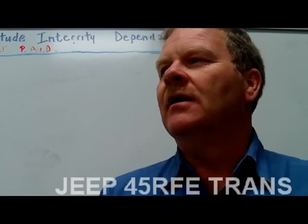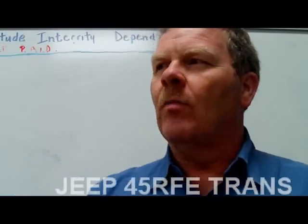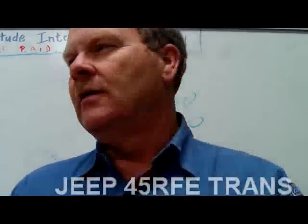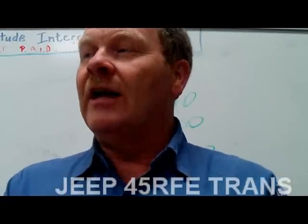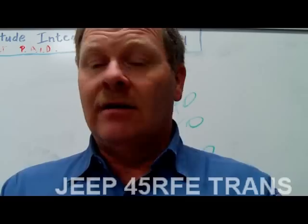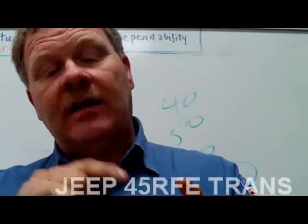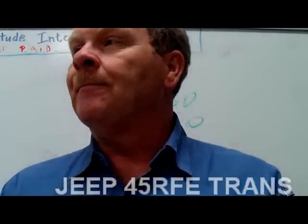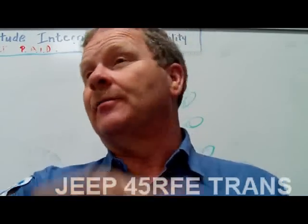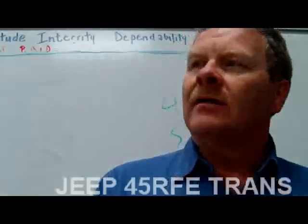The speed sensor on that Cobalt was hardwired to the transmission control module, and the speed information was sent to the instrument cluster on the Class 2 signal line. So I had like 9,000 ohms coming from my vehicle speed sensor, and I had a good signal coming up that way, all the way to the connector. I'm checking it right here at the transmission connector, not at the sensor. I've got everything I need right there, but this thing's dead as a hammer. And so I call over here. They get me a used one, $100, and pop it in there. And we got speedometer. We got shifts and everything. Didn't even have to program that one.